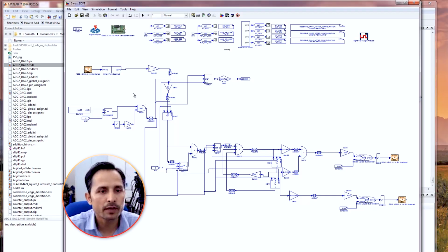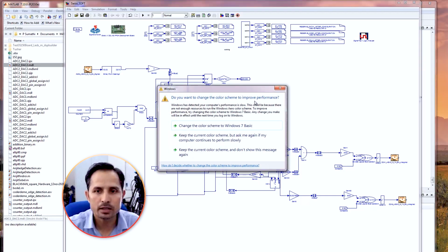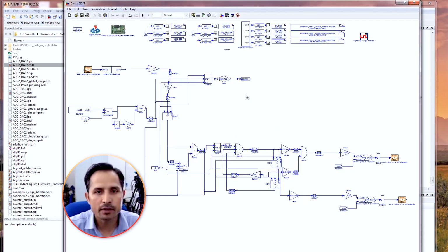So this overall program is to reduce the sampling frequency basically. If I do not use this one, then the overall program will be working for a 50 megahertz signal. So it will be very high frequency. But right now what we are doing is dividing this 50 megahertz clock signal by 20. So right now this block will be giving a sampling frequency of around 2.5 megahertz. So 50 megahertz divided by 20, almost around 2.5 megahertz.